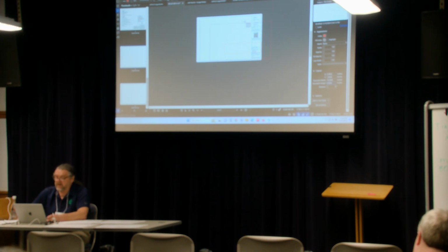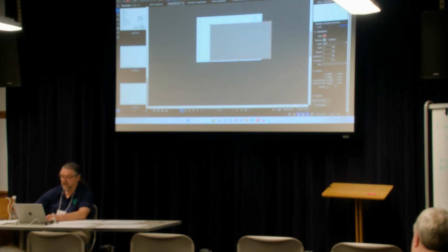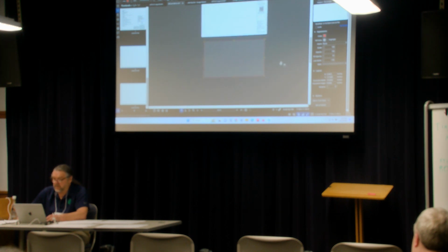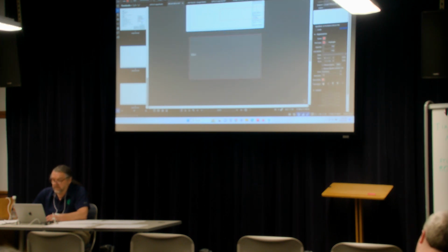One of the things that I get frustrated about is that I can't grab this empty part. So what I'm going to do is select this, and I'm going to fill it with gray, and I'm going to turn that gray to 20%. So it's translucent, but it gives me a place to grab here. So what I'm going to do is dimension this, and it's going to want to scale, and I'm just going to pick one at random. We'll do a 1/2 inch equals a foot. So now dimension this.